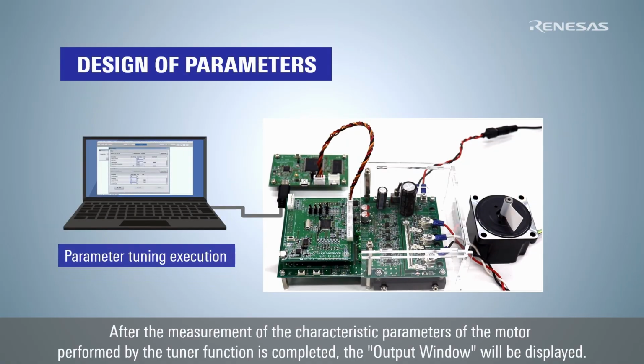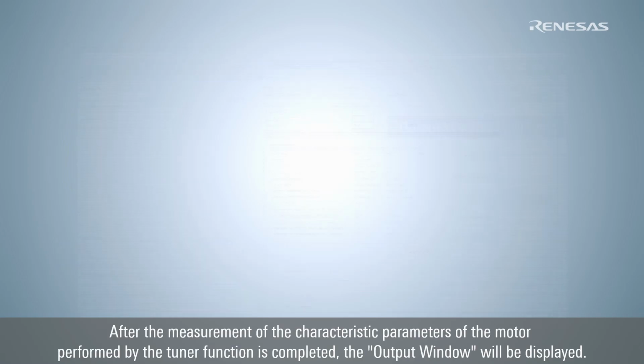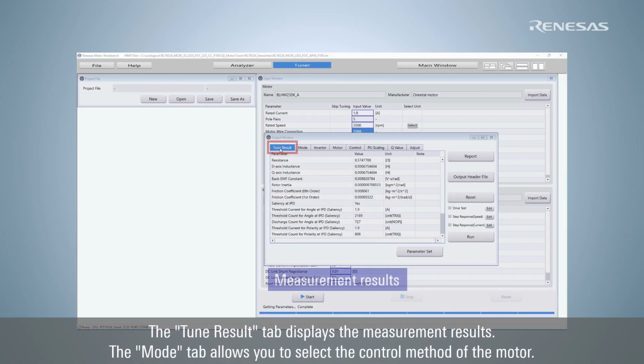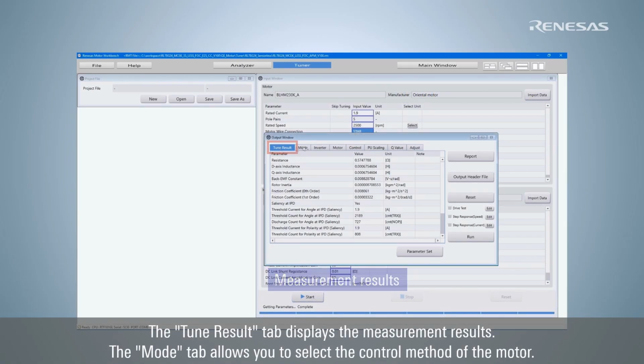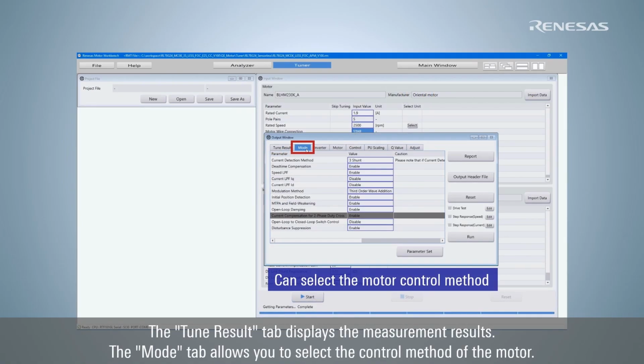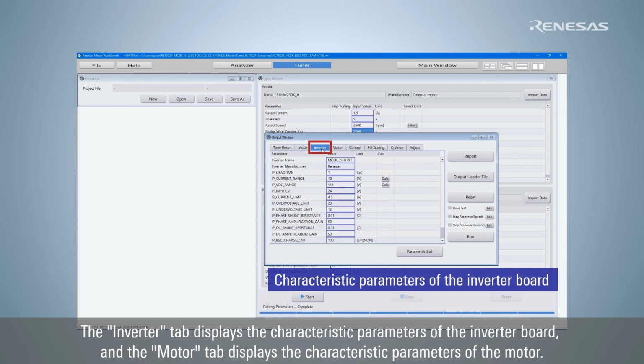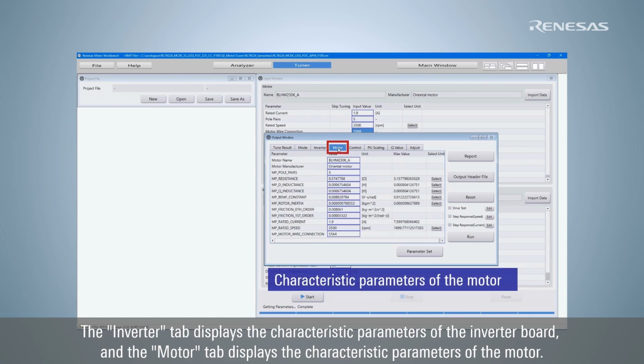After the measurement of the characteristic parameters of the motor performed by the tuner function launched from the QE for motor is completed, the output window will be displayed. The Tune Result tab displays the measurement results. The Mode tab allows you to select the control method of the motor. The Inverter tab displays the characteristic parameters of the inverter board, and the Motor tab displays the characteristic parameters of the motor.